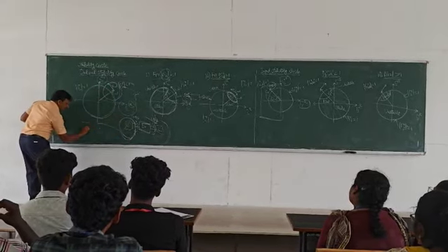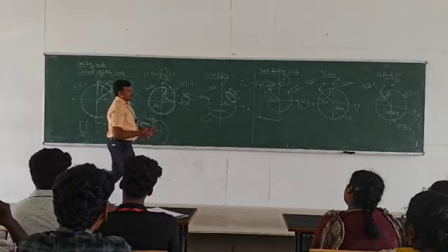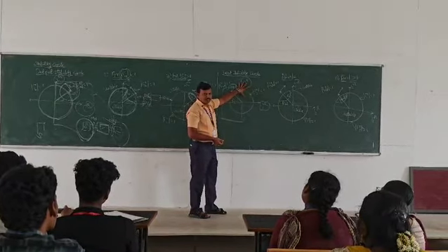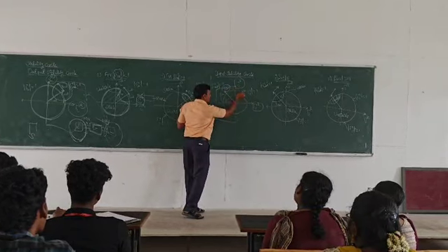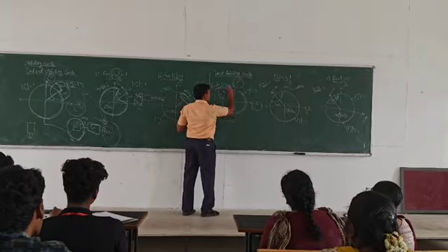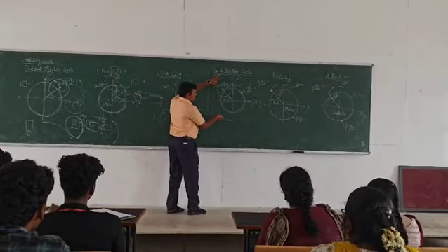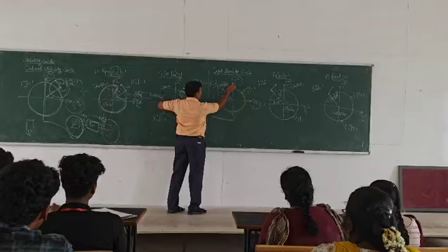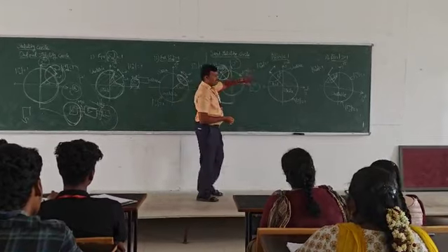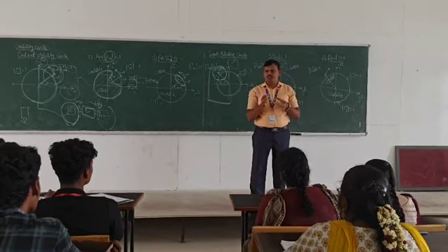So we represent the source reflection coefficient gamma s. First we have to draw the main stability circle at the input side. We draw the major circle first, and then draw the smaller circle, which is mapped to the main circle. These two portions are referred to as the input side, because we are now focusing on the source side. This is the smaller circle. Now we are considering port 2, S22, which is the port 2 reflection coefficient.